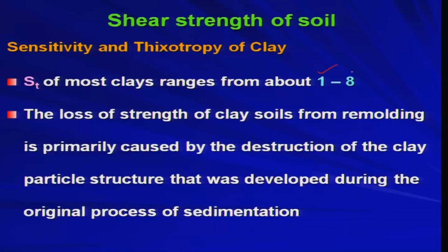Now, when you are collecting the soil, though you are not changing the moisture content, you are still disturbing the structure that the soil originally had. Due to this destruction of the structure, you will get a lower strength. Whatever strength you are supposed to get in the field, you will get a lesser value of shear strength in the laboratory.